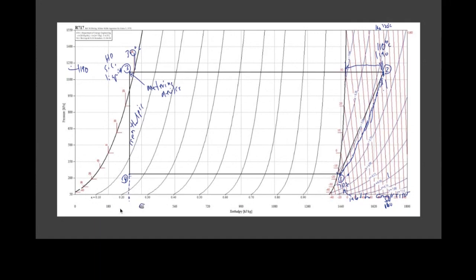Well, that's 180, that's 360, and I don't know, let's say that's 250. I'm just guessing right now. What's the unit? Kilojoules per kilogram, so this is specific enthalpy. If I know how many kilograms I'm circulating per unit time, then I know, well, actually, I'll get to that point next. So it's coming in at 250 kilojoules per kilogram, and it's boiling.